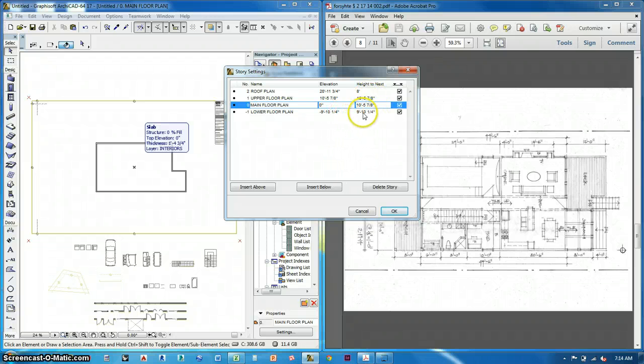The lower floor plan we might want to adjust. That would be 8'8" minus the 4-inch slab plus the 1.5" plate at the top of the concrete wall plus 16 3/4. A little tricky, but it should work out to be 9'10 1/8". So these should be right.